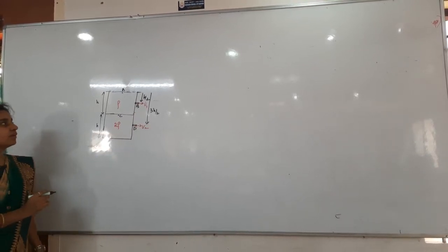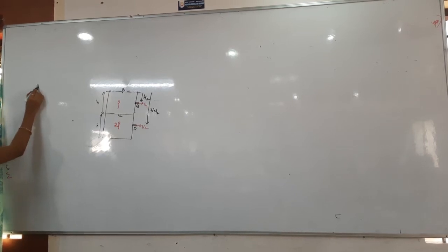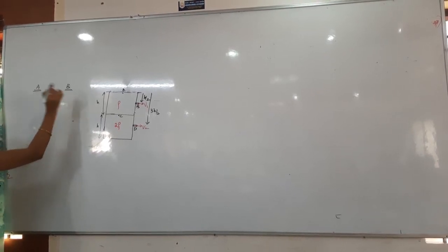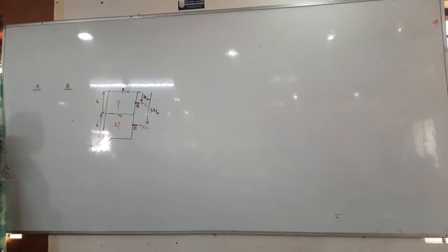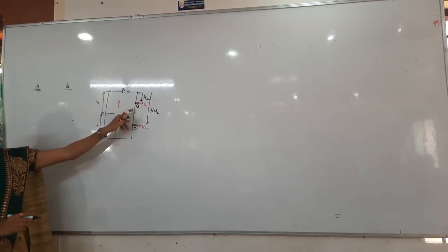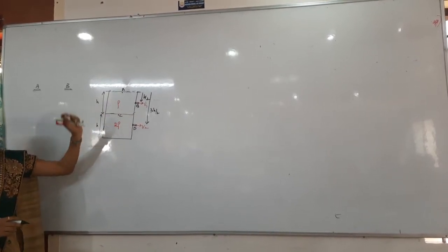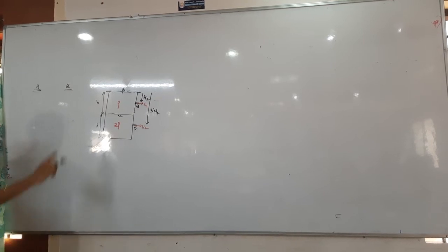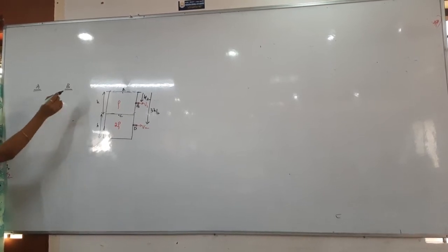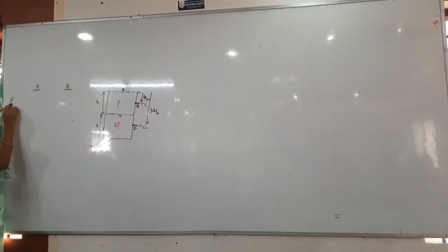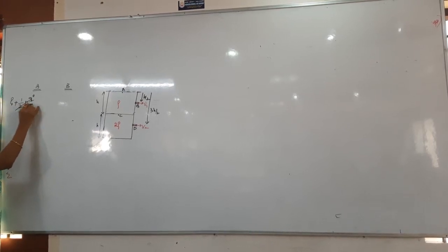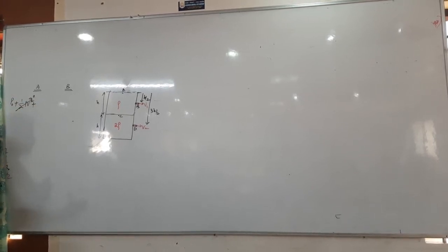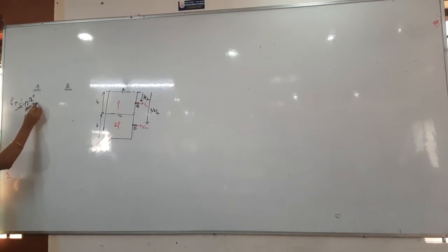First, let me apply Bernoulli's principle at point A and then B. The points A and B are in the liquid of which density? Rho is the liquid density here. Now, point A pressure: atmospheric pressure P0 is there on the top, open end. Then P0 plus kinetic energy, half rho V square, becomes 0. Why? Because the liquid is falling freely here.